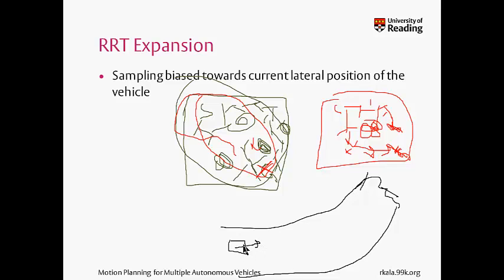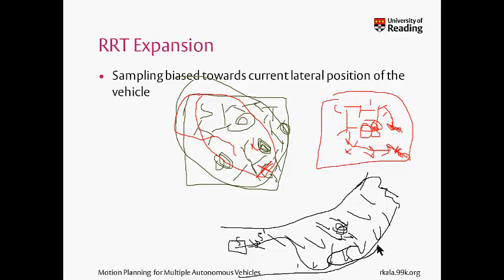If this was the vehicle, this was the source, this was the effective source after the heading angle. Now we know the vehicle will most probably not like to come into these areas because it will ultimately require such large steering. It will prefer to stay mostly in this region. If there's some obstacle here, it might go here, it might go here, but it will be completely unpreferable to go in regions very far off.